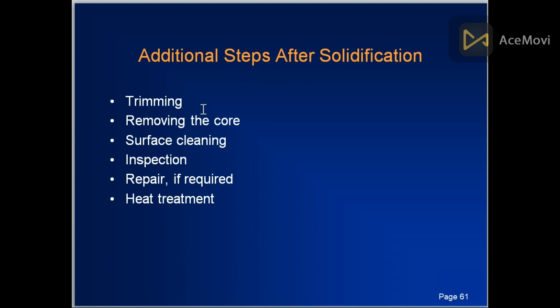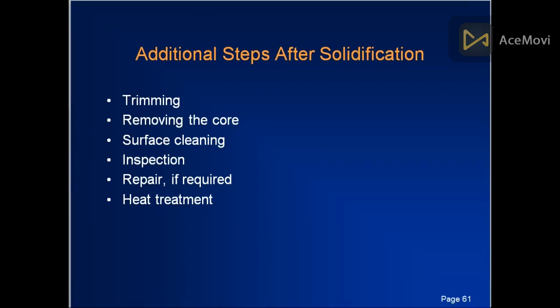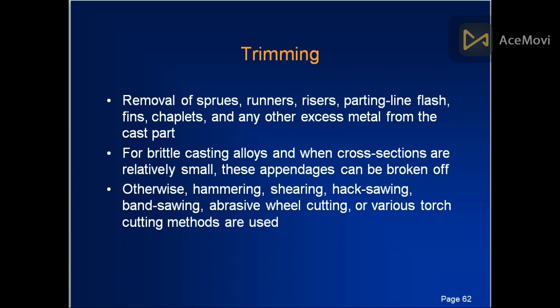Additional steps after solidification include trimming, removing the core, surface cleaning, inspection, repairing if required, and also heat treatment. Trimming includes removal of sprues, runners, sleeves that are some extra material, flashes, fins, and chaplets. The removal of all the extra things is known as trimming.